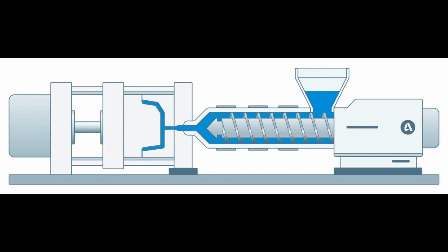The temperature of the mold affects how quickly the material cools. Finally, the speed with which the material is injected can have a large effect on the pressure required to fill the part. Too fast or too slow, and the part will not fill.